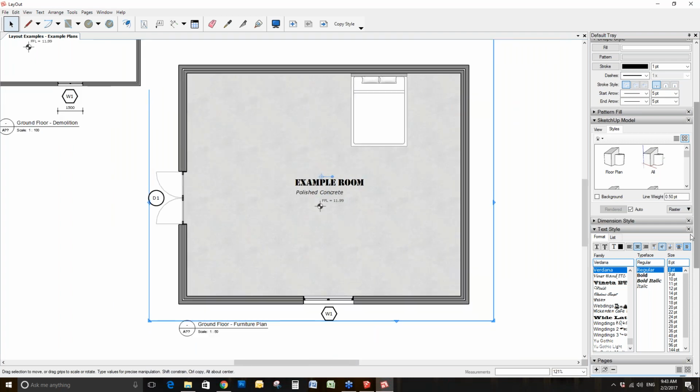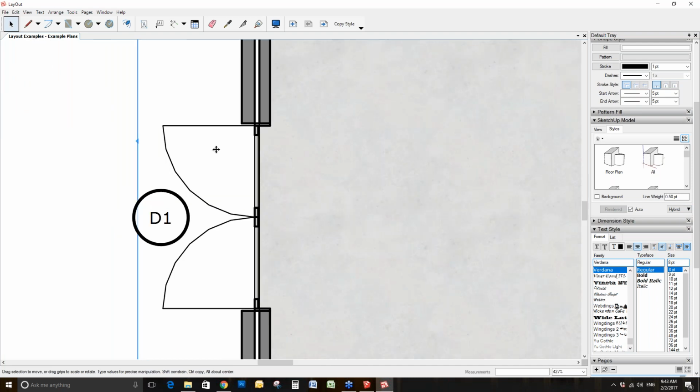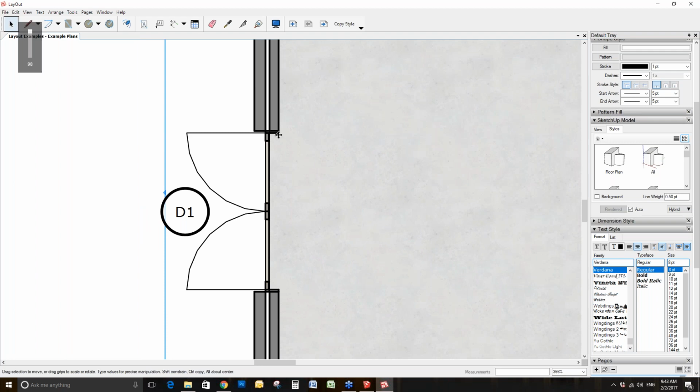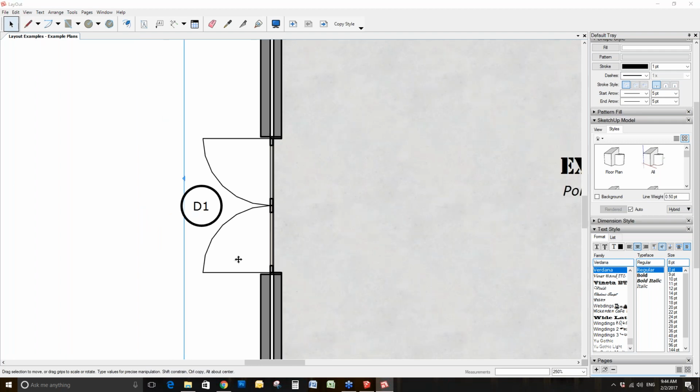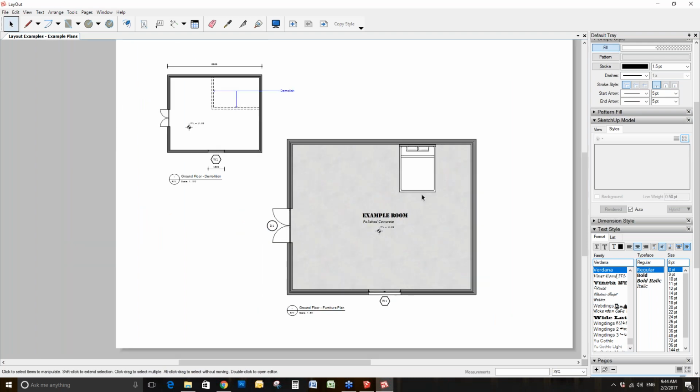So if you want to create very nice looking lines, but show color and texture too, you're going to be using hybrid. And hybrid is the best one to use with your PlusSpec model. It's the one that I recommend. And that gives you the best of both worlds. It gives you the color and texture as well as the line and the line quality. However, if you're doing traditional 2D black and white, you might actually want to set it to vector.